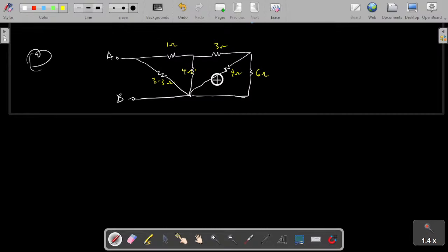How do you find the effective resistance? We need to find the total resistance across these two terminals. Okay, please, whenever you are finding the effective resistance in any electrical network, don't be scared about the complexity of the arrangement of resistors. Just go by principles. By principle, we take two resistors at a time, and you should always start away from your source, away from your terminal, then you simplify close to the terminal.